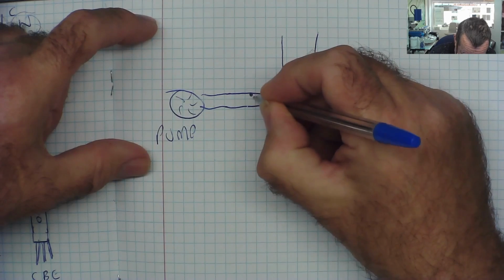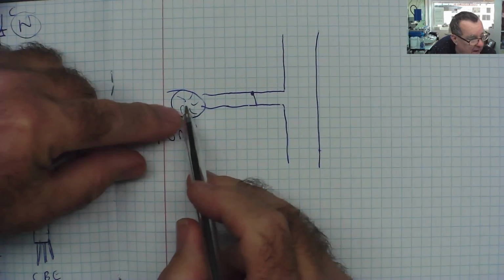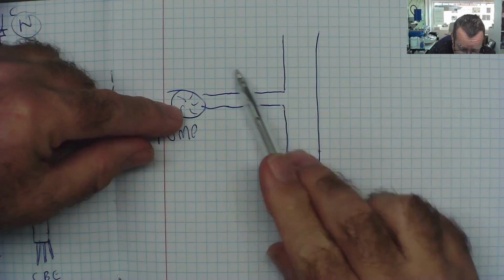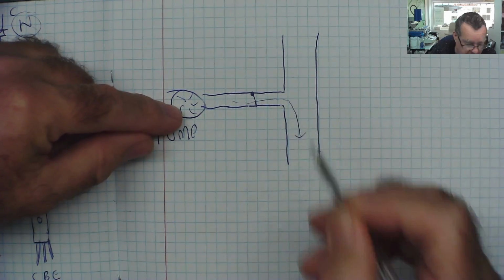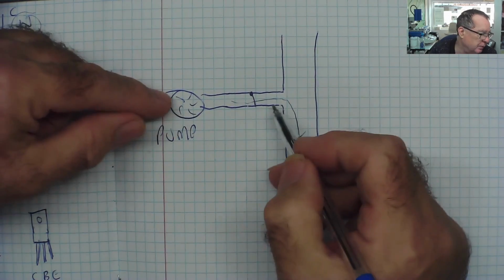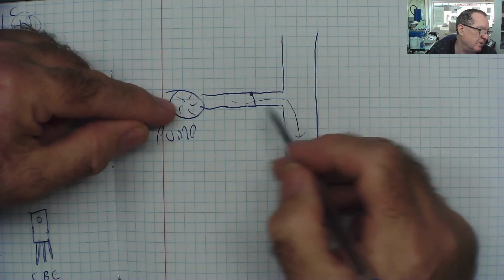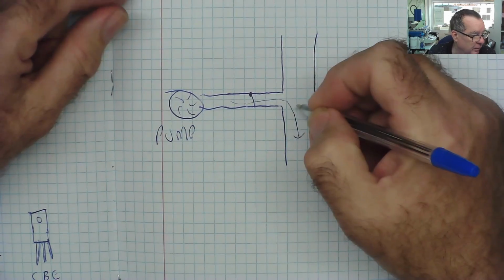So the valve effectively is pivoted and sits here. And as you apply pressure, you open the valve, allowing water to flow through here. But until you apply a certain amount of pressure, no water will flow. It takes a certain amount of pressure to overcome the inertia, the mass of the valve before it will open.